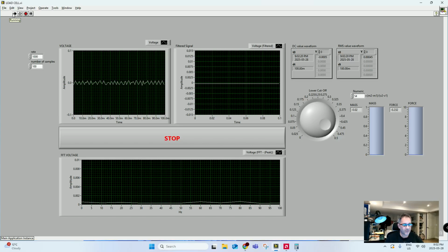And as you can see, there is now a deviation of the value, the fluctuation that went below zero. So this fantastic load cell amplifier has a couple of screws on the back that allow you to zero the signal, the voltage. It is explicitly written.